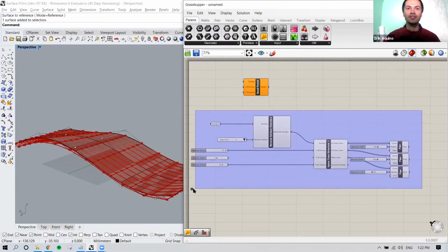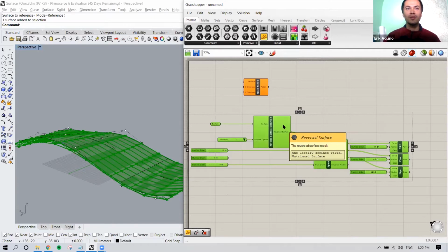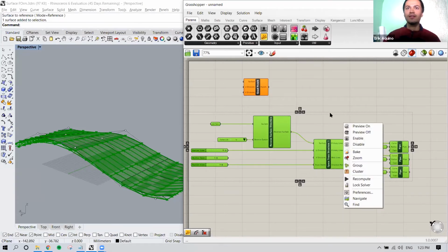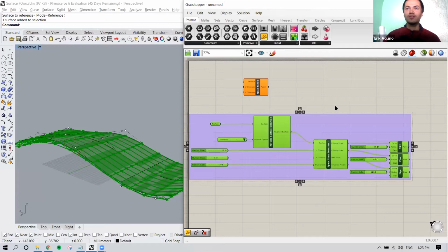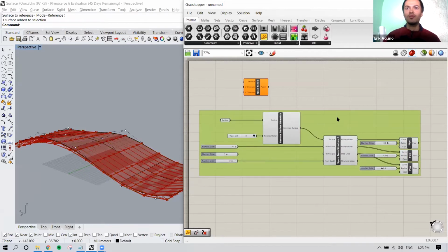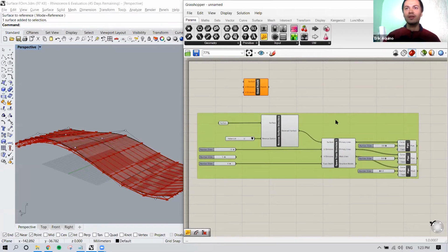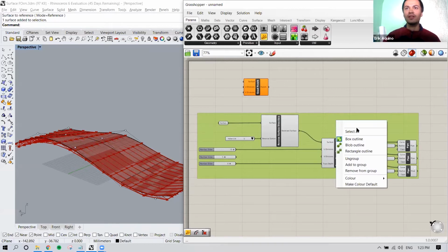So I'll select all my components for this base frame, and I'll right-click outside on the workspace and then group these, to which I could move these around now freely as one item, and even right-click to give it a name. So I will call it space frame.